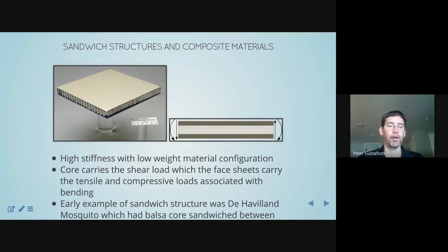One thing that you're going to see as a common theme is a move towards composite materials. I showed that 787. The 787 is over 50% by mass structurally composite rather than aluminum or steel. Now that is a massive change, and this is the next generation of aircraft that are being brought into service now. Where does composite material fit in comparison to aluminum and other structural metals? Composite structures tend to be designed to have very high stiffnesses but with very low weights.